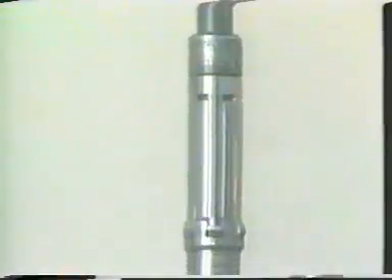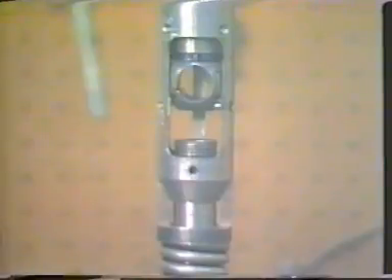The pressure-sensitive valve uses the existing wellbore pressure to control the safety valve. This type of valve makes use of a pressurized dome or bellows which is charged at the surface. If the wellbore pressure drops below the dome pressure and spring tension, as in the case of high-velocity uncontrolled flow, the valve closes.